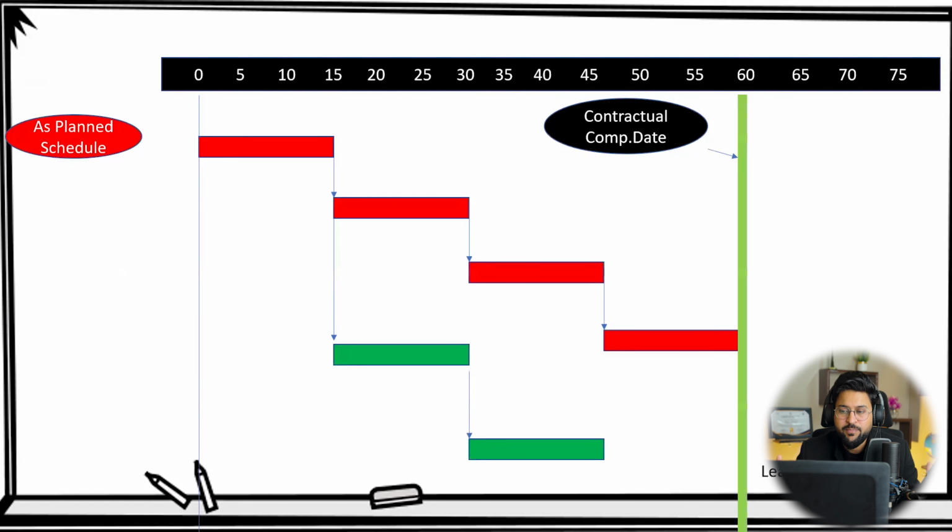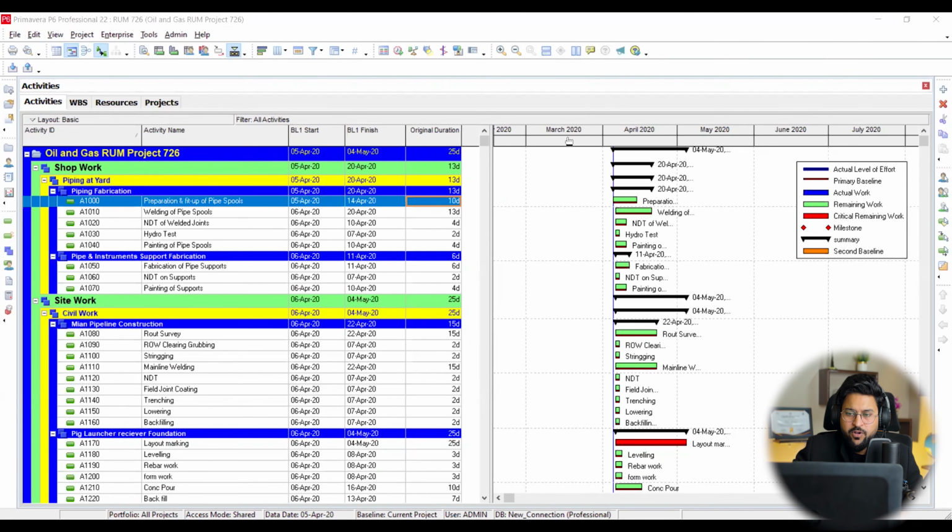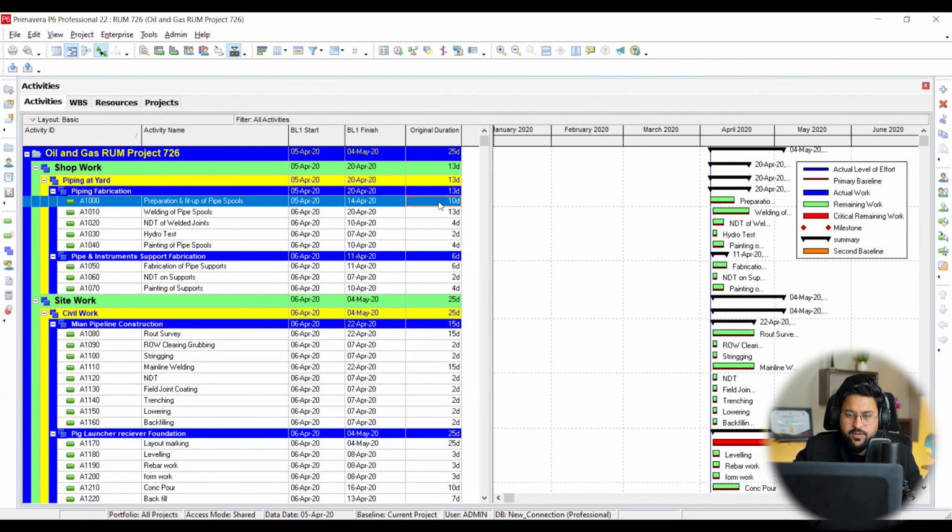And this is called the critical path method. It is going to conclude the critical path, the longest path in which your project can be completed in the shortest possible way. It is going to diagnose the float and non-critical activities as well, right? So these are the two most important things. But relationships will be concluded from construction strategy, from your company strategy. There are two important parameters I'm going to share with you. So now let me perform on Primavera P6 how to do that one.